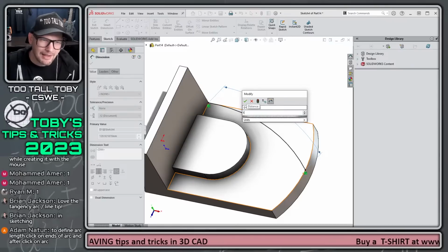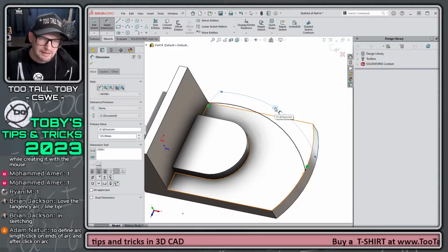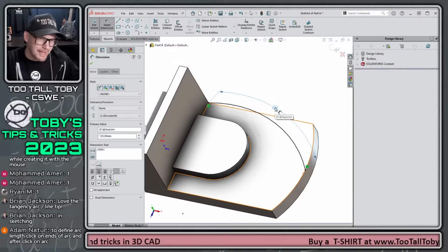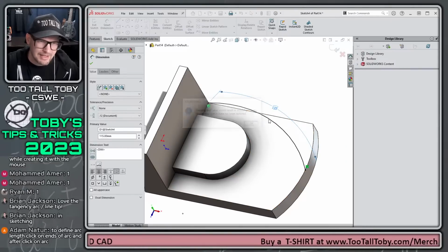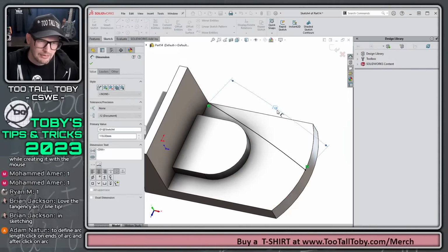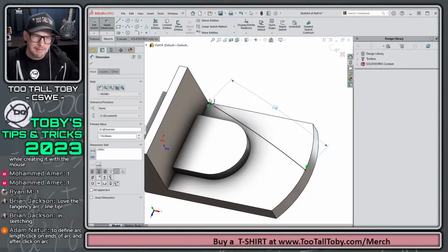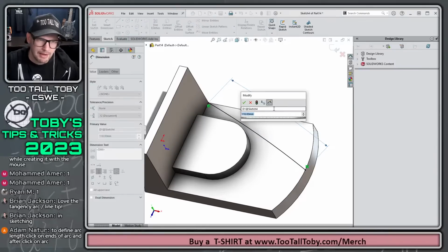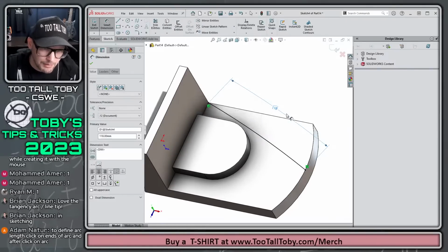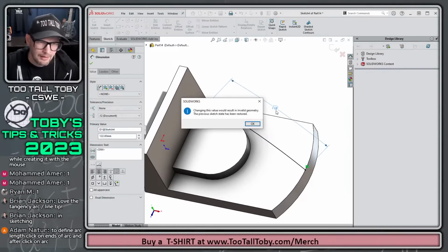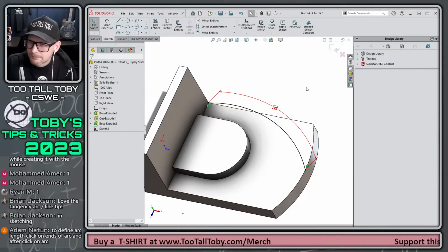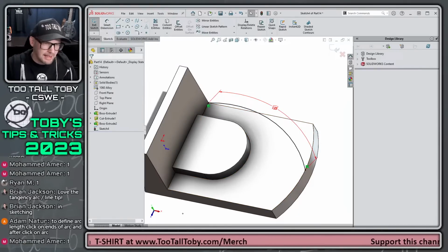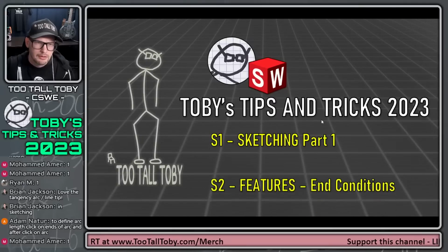But if we make that, say, 125, then you can see that the radius gets more, you have more cable that you have to fit in there. If we make this 115, then actually you can't even get that short. If we make it 118, now you can see it's almost a straight line. We only have that much cable to get through there. So we'll make it 120, and that way we'll have a little bit of arc. It doesn't want to let me get back to what I was. Yeah, good tip there, Adam. Appreciate that. All right, cool.